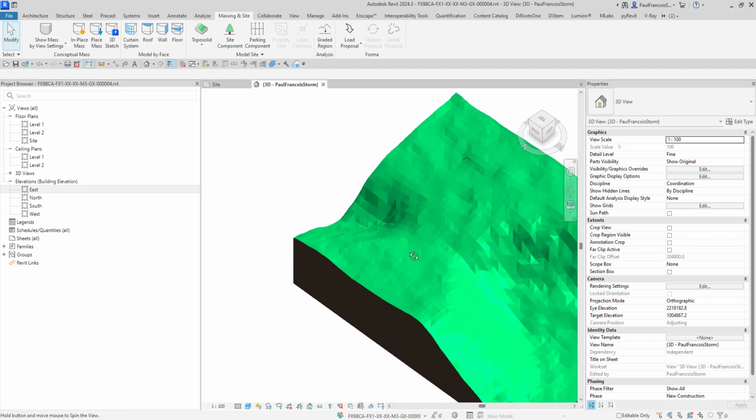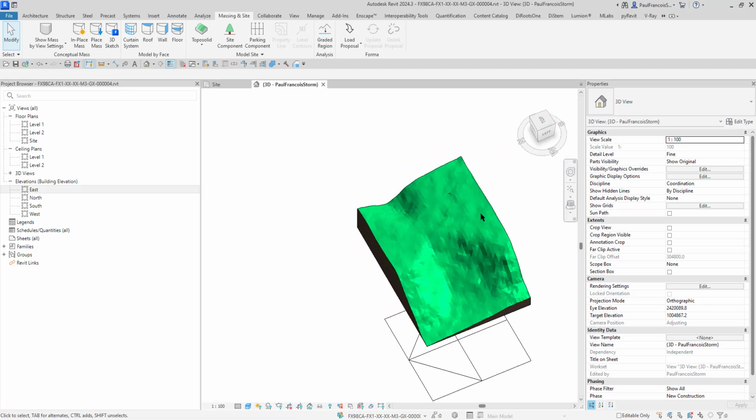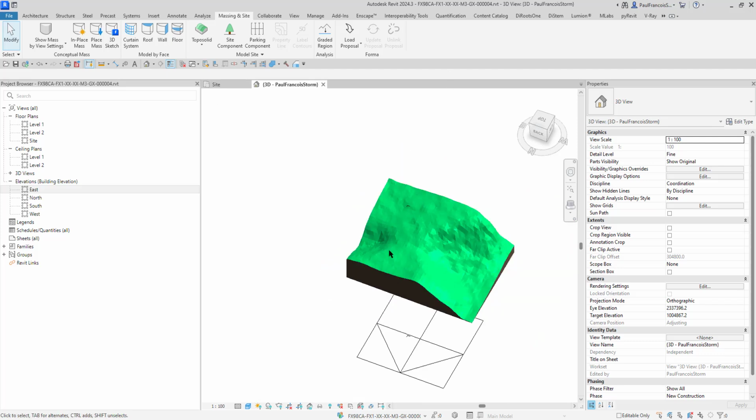And now we can use this to set up our site model. For those of you that understand how to take this process further, we won't do that today, maybe in the next blog. The next idea is then to bring the buildings in. And how we do that is we link this topography file, this site container, into the models that we want to host in here, and then we acquire the coordinates from this Revit file.